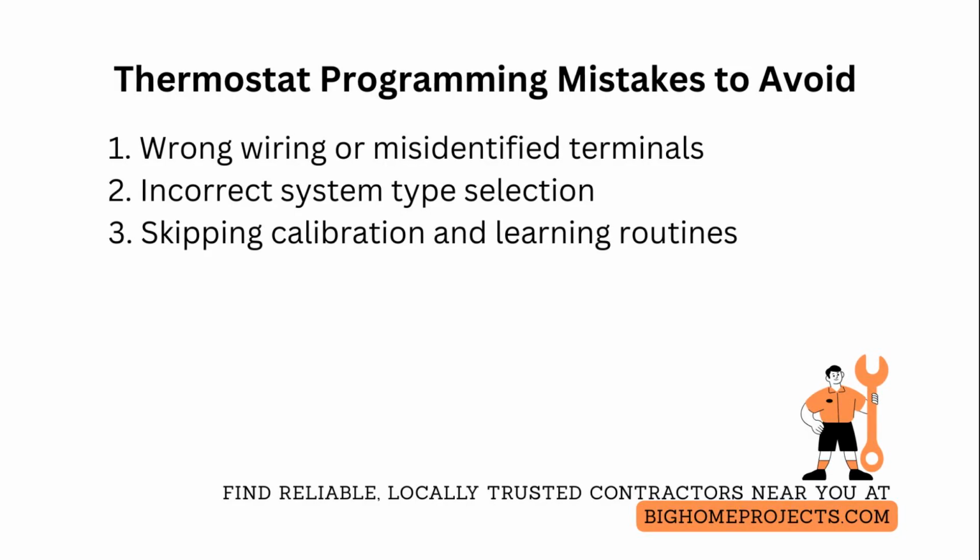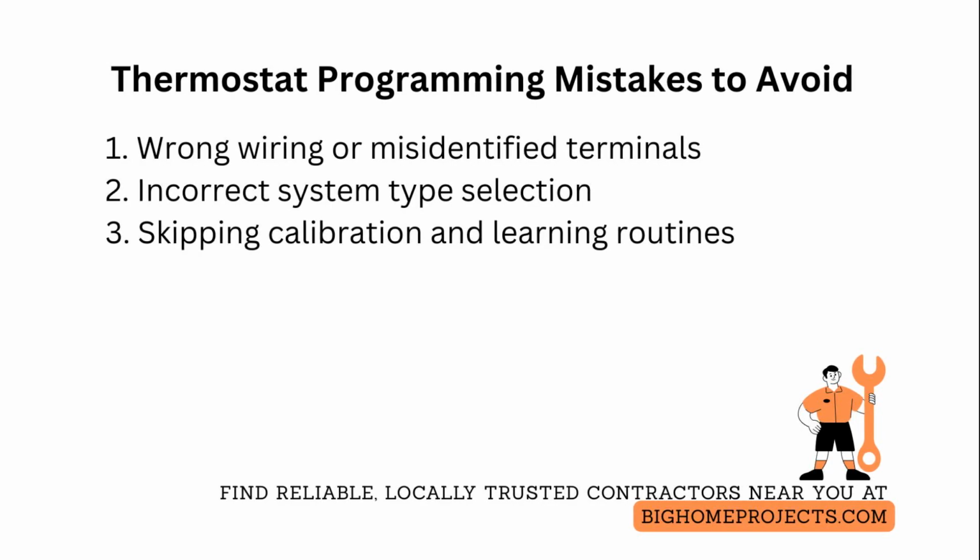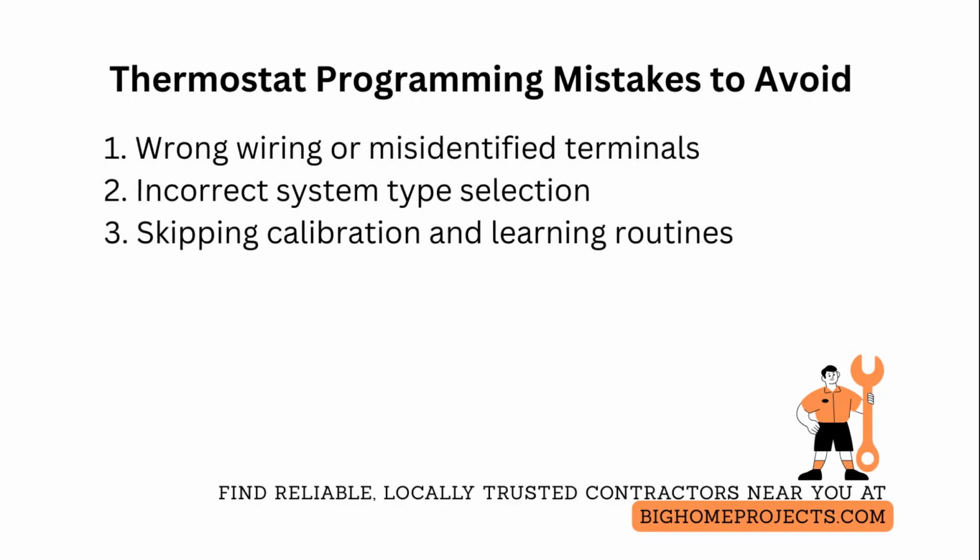Third is skipping calibration and learning routines, resulting in frequent short cycling or improper stage sequencing. Fix by running built-in calibration, setting minimum run times, and configuring stage thresholds and lockouts per the manual.